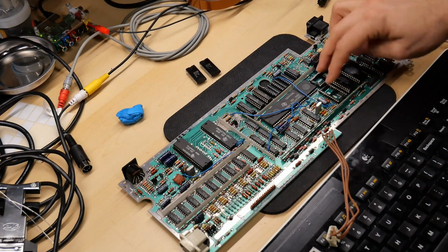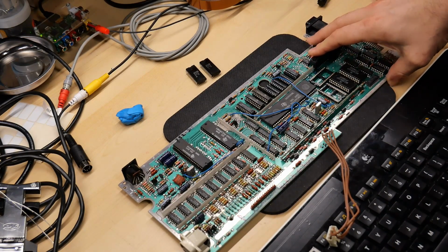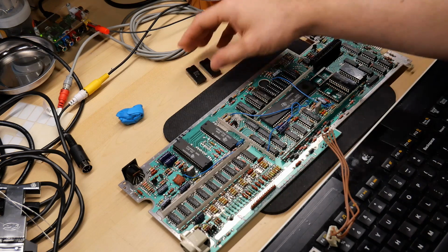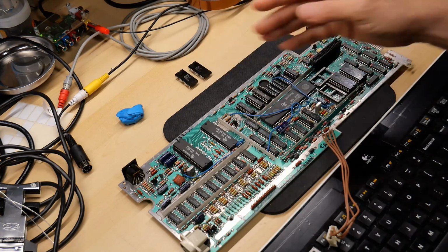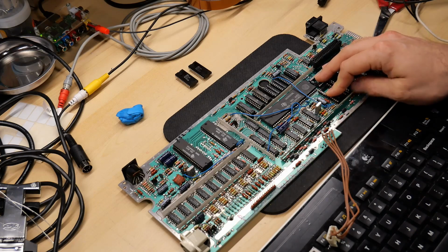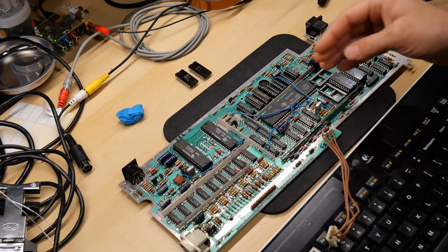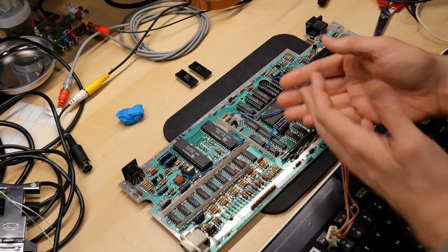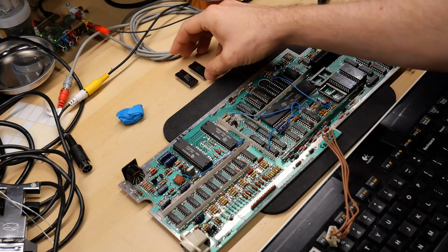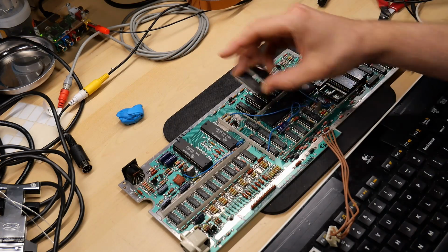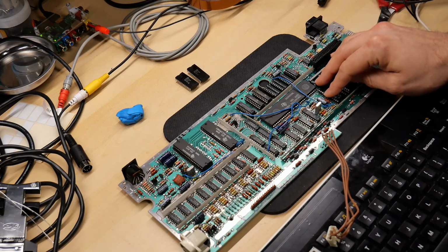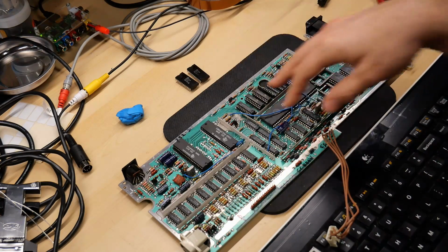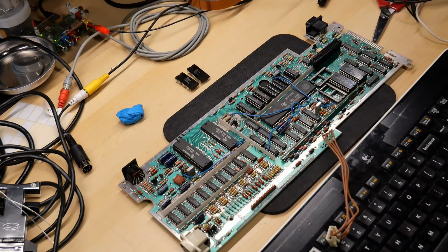Well, you can see that I have these sockets installed in the board, but I've gone ahead and tested, and yeah, of course, with these ROMs in there, it's not working. But when I pull the ROMs out, it kind of looks like the problem goes away. I won't show the oscilloscope results, but the computer also is not doing anything anymore because, of course, the CPU needs the ROMs to try to do something. So it sits there trying to read the ROMs out. And of course, they're not working, so everything is just sort of dead.